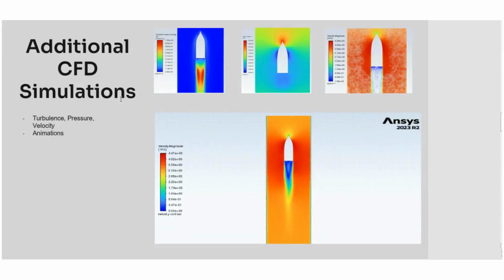So, after we did our preliminary simulations that we just showed, we moved on to doing more complex simulations now that we've actually developed a skill with the software. The first one we did was here with a top view of our boat. This view is developed by finding the waterline of our boat and then importing that profile as a geometry file into ANSYS, and then using that for our simulations.